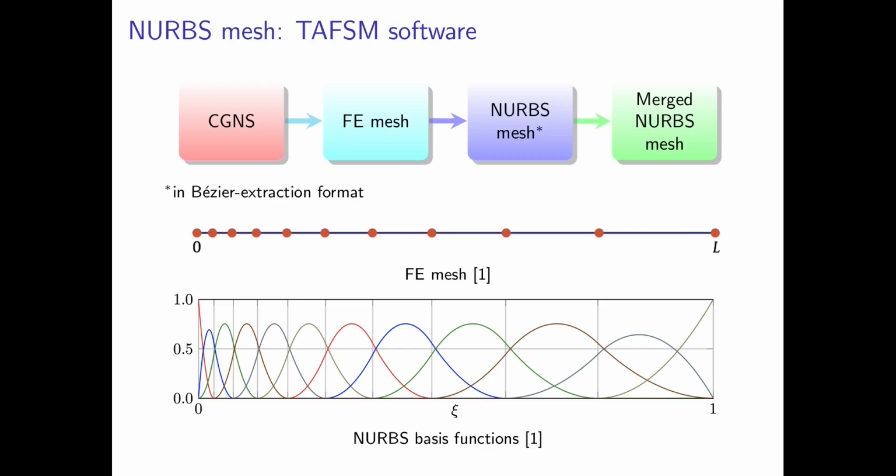CFD General Notation System. CGNS files are topologically based. That implies that a file in this format is organized by zones, and each zone contains similar information, such as grid coordinates and multi-zone interface connectivity. For a block-structured mesh, the zones represent the blocks. If you're using Pointwise to generate the block-structured mesh, when you export a CGNS file, it will automatically write the